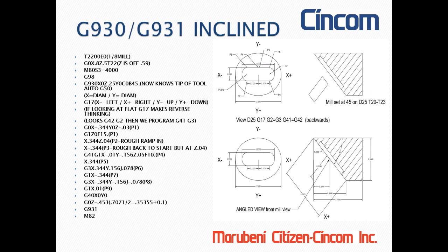Now, when we use CAM systems, you can do some settings and ask your CAM software people. The code can come out as 3+2 or 4+1, so they can break it down and do many small moves to be, I'm making up my own words, 98% like a 5-axis, but it's not true 5-axis.